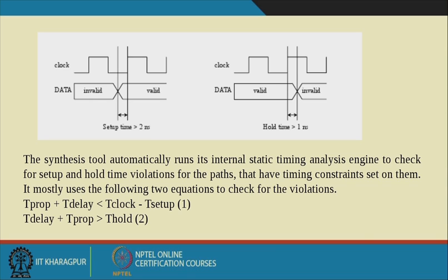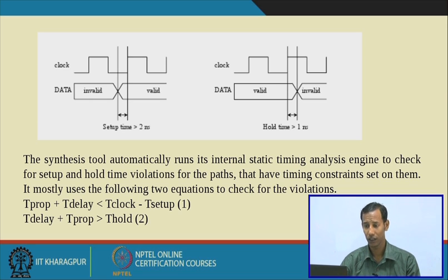So this is one of the examples. Whenever this clock edge occurs, you see here this portion, basically in this line, this is the setup time. So before this clock edge, what time is required where the data is not changed? This time is known as the setup time. Here the setup time value is 2 nanoseconds.